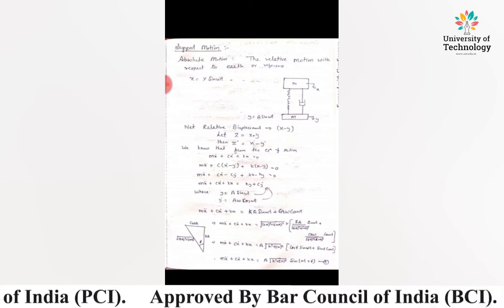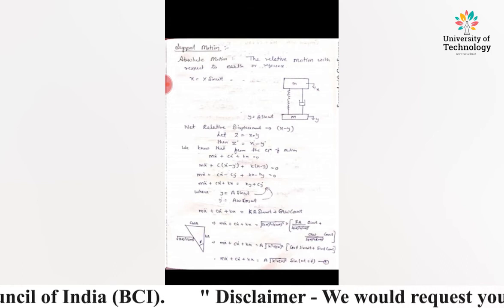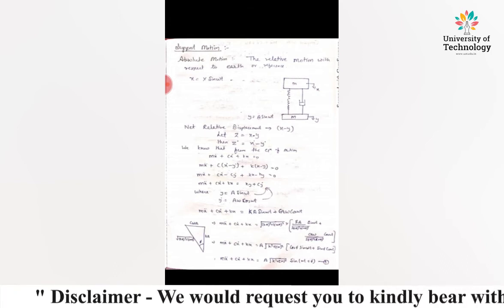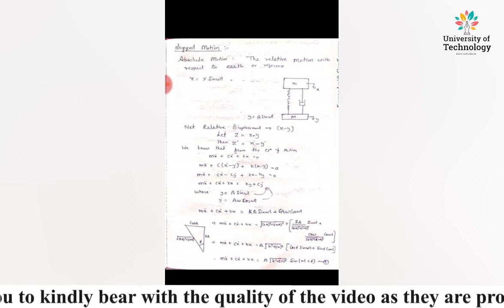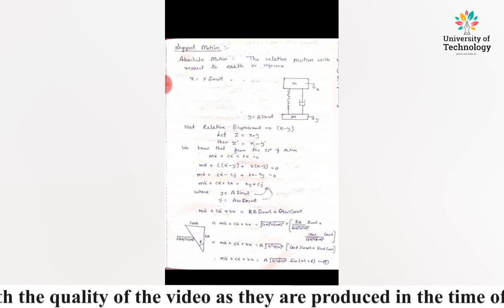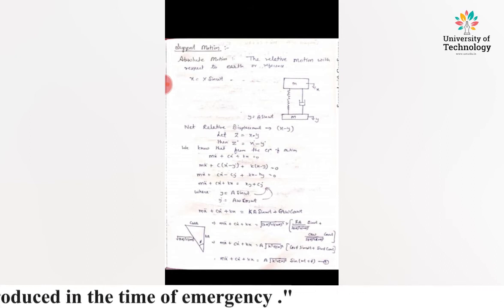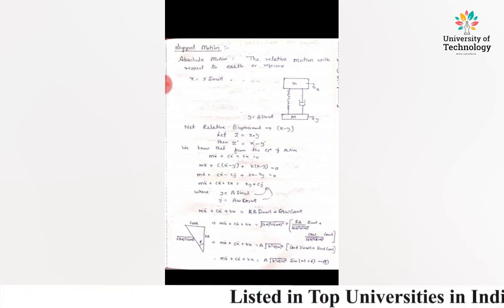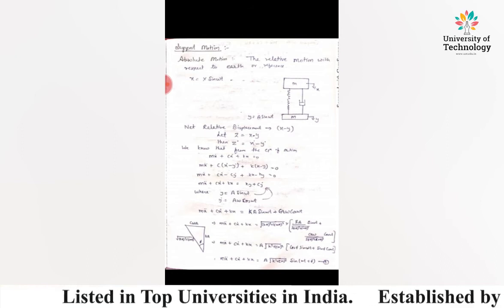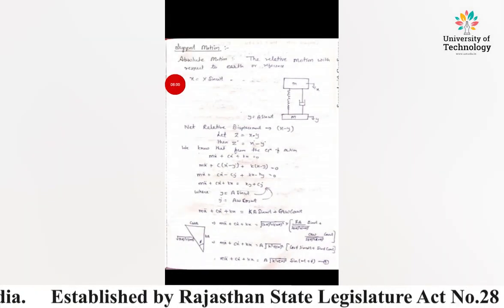This is the mathematical identity cos A sin B plus sin A cos B is equal to sin (A plus B). Here A is equal to omega t and B is equal to phi. Then the equation will be m x double dot plus c x dot plus kx is equal to A root of k square plus (c omega) square times sin (omega t plus phi).